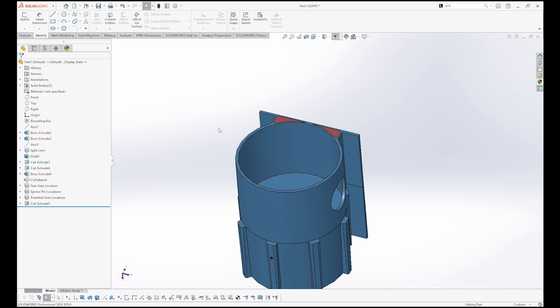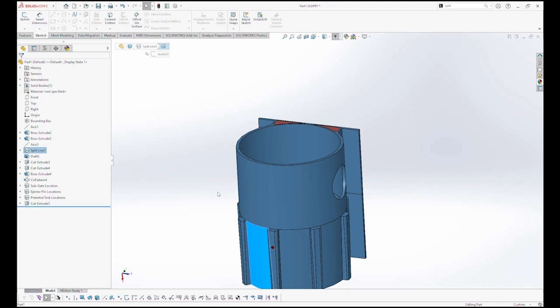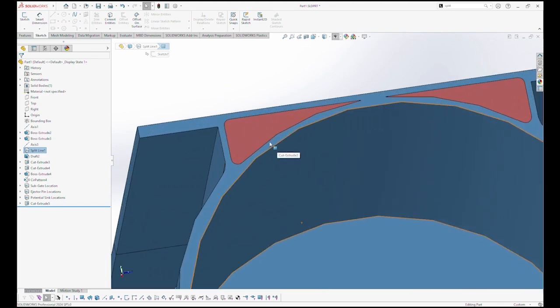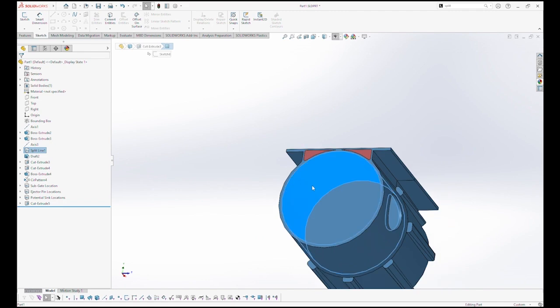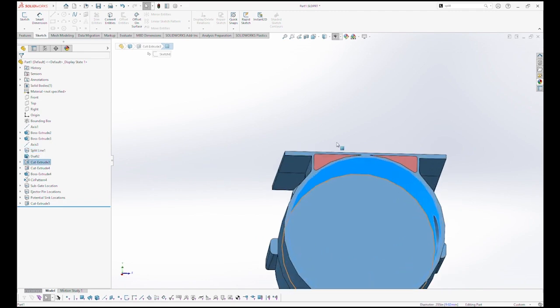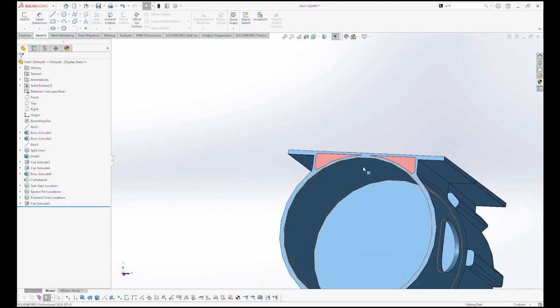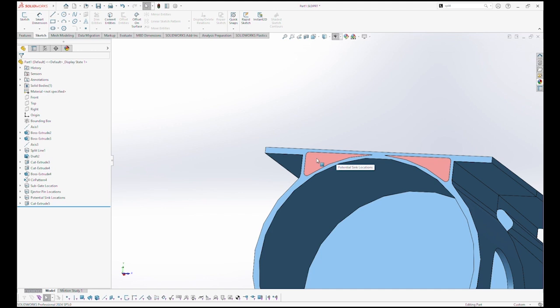So remember, we had the top half, what not to do, the bottom half, what to do. And I would just like to pause and talk about it in a little more detail. Because we just did a circle extrude and a cut there, it left a little bit of thickness here, which is represented by these two triangles. And basically, the heat in that area is going to remain there longer than the heat in these 10 thousandths thick wall sections.